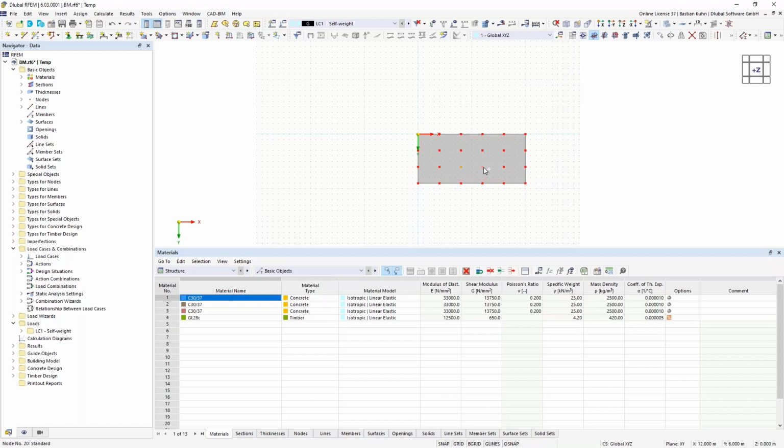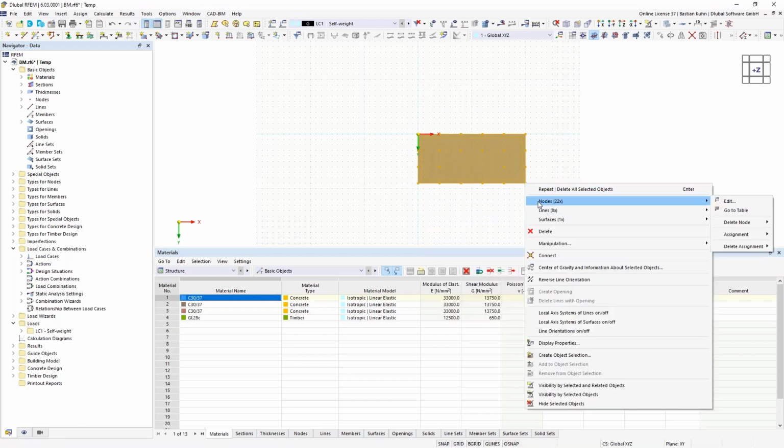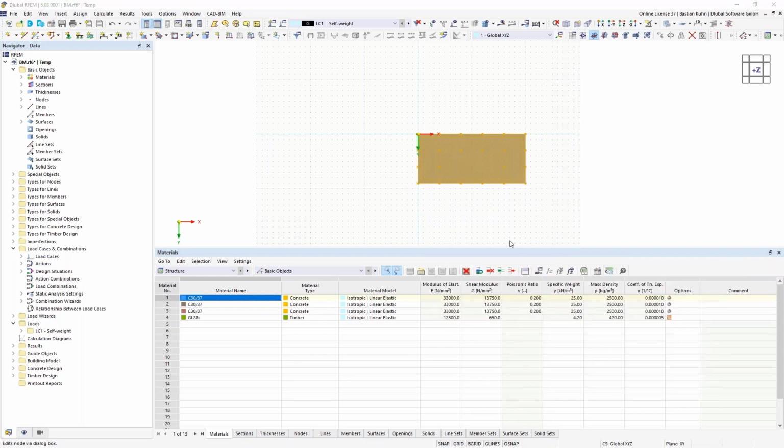I will do the stiffening of the structure by a so-called concrete kernel, which will be arranged from these nodes that are highlighted in here, and therefore I will delete the 2 nodes there in the front. The first story should have a height of 3 meters.